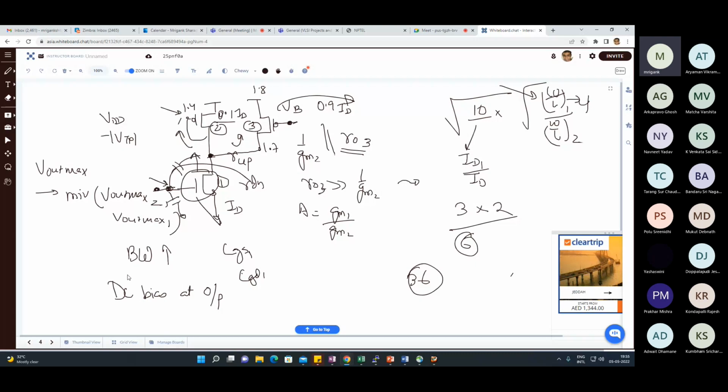So that is also another advantage. So as compared to only the diode connected load, you get a higher bandwidth, a much more stable DC bias point and a deterministic gain. Overall magnitude of gain may be still lower than what you can get only using current source load, but a stable DC bias, clear deterministic gain, and then higher bandwidth. Is that clear?